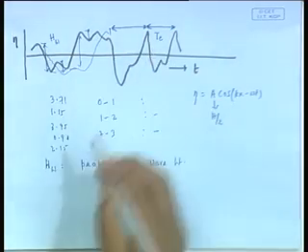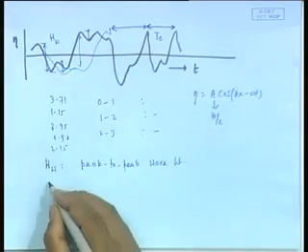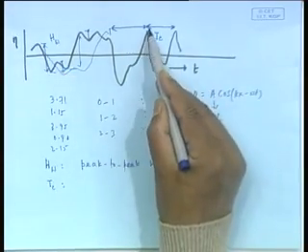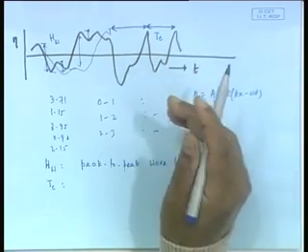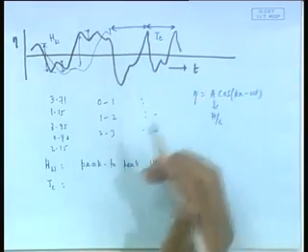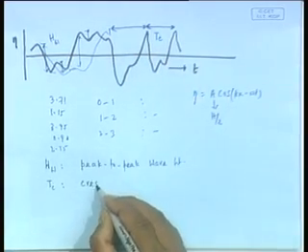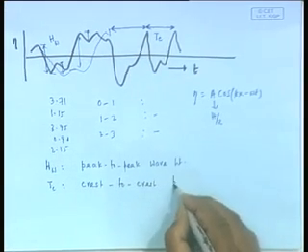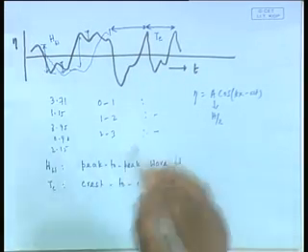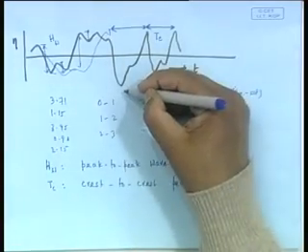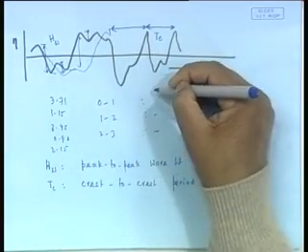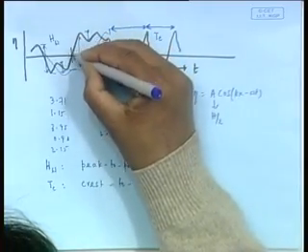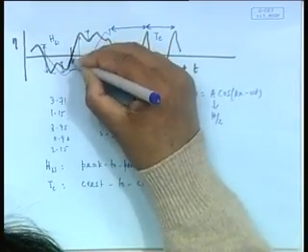That is one thing. Now, coming to the period side, I can have one period Tc, which is when I measure the time interval between successive crests; this is called the crest to crest period. Of course, you can always say I can have a trough to trough period, but normally it is not used. Another very important period is where the signal crosses the 0 line.